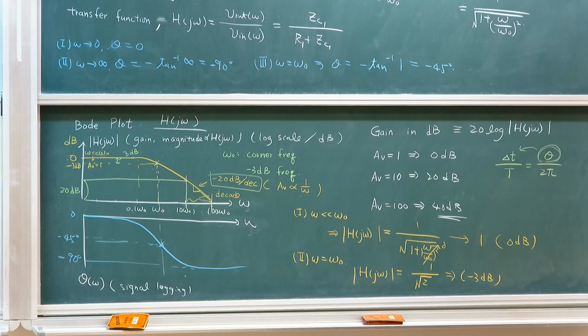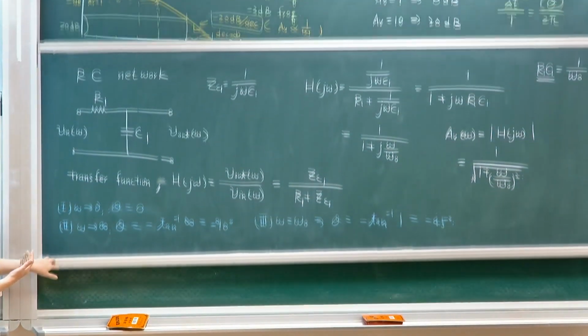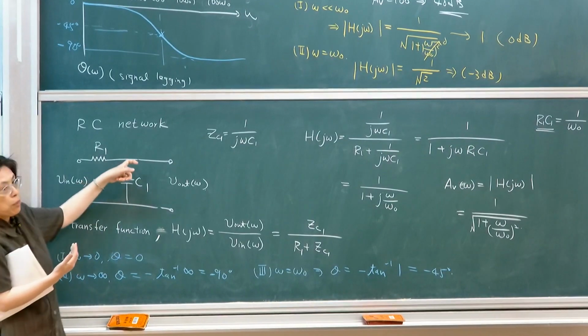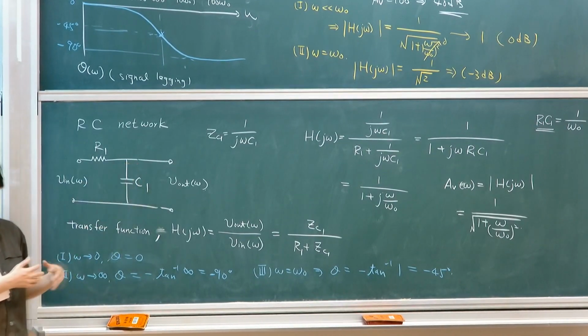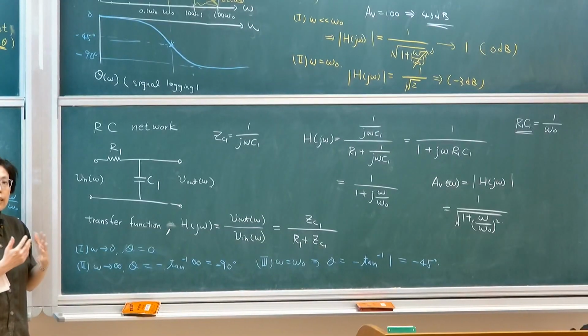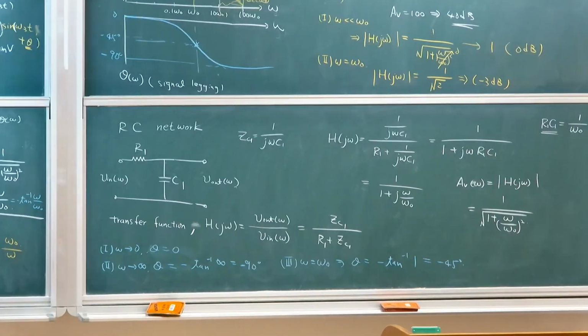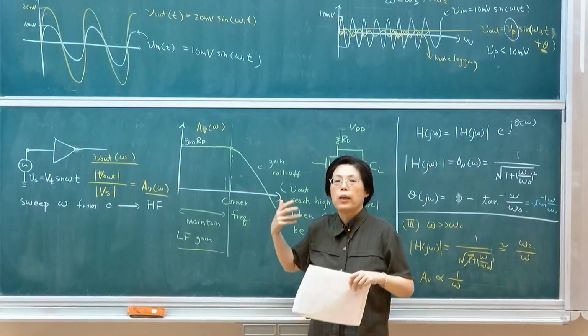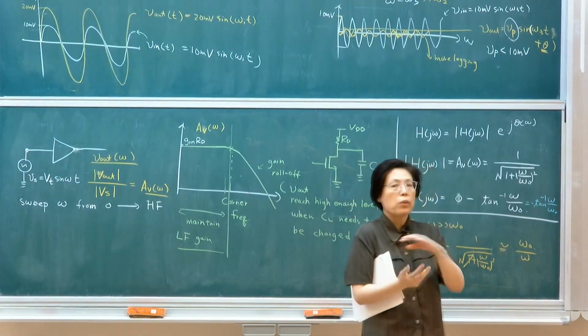You need to be aware that having these capacitive components will lead to a scaling in your magnitude, because we know that it needs time to charge up the capacitance. Once frequency increases, you may not reach the peak level that is desired. So there's a lagging in time and also a reduction of magnitude.